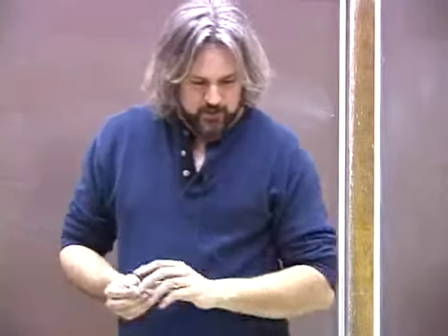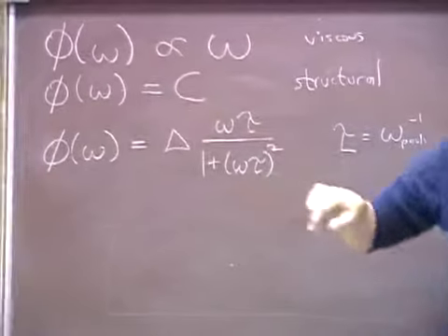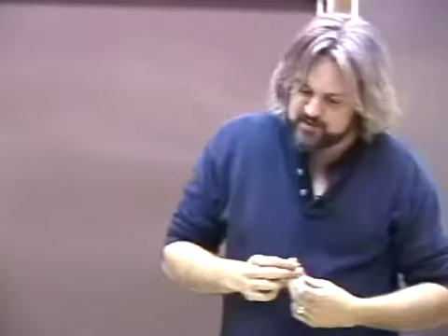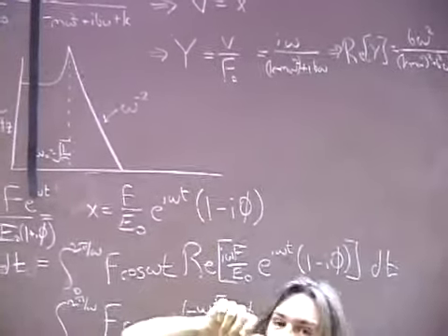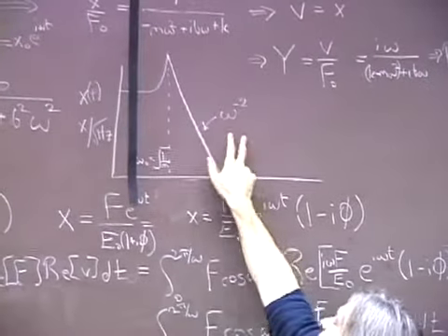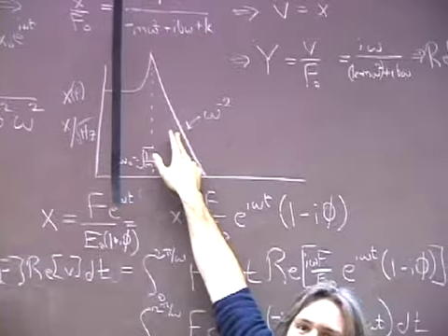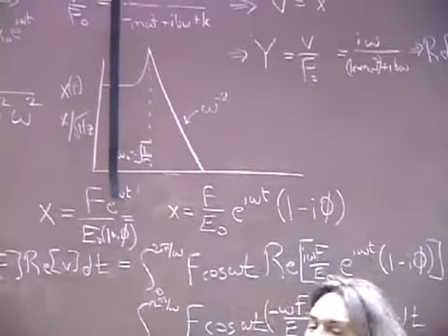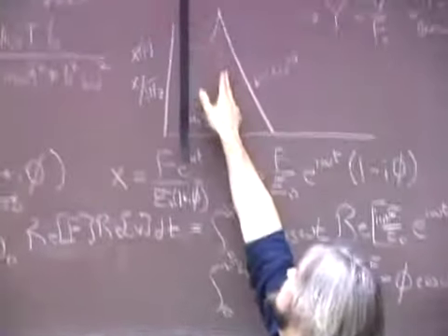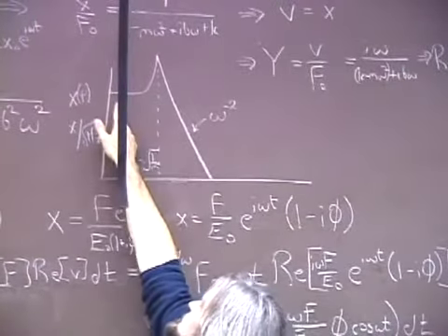There are 2 approaches you can use. One is just to reduce or eliminate the sources of damping wherever you find them. The other is to design the mechanical system so that you can push the thermal noise, for example, this thermal noise, into some uninteresting frequency. For example, if you're looking for gravitational waves here, this pendulum thermal noise is not a big deal. If we're looking for gravitational waves here, it's a very big problem. We would want to design the detector so that this peak is perhaps over here.